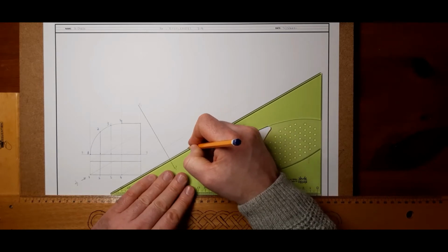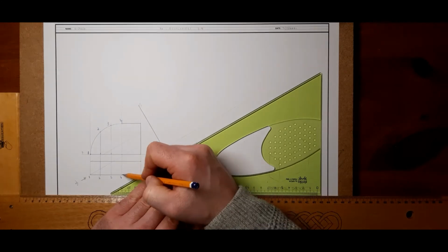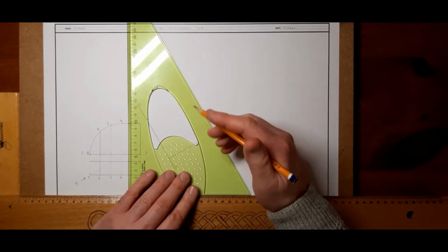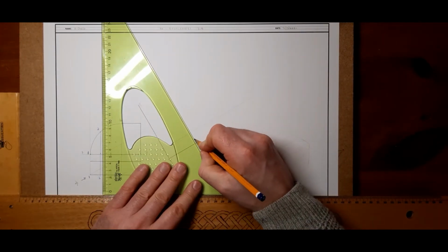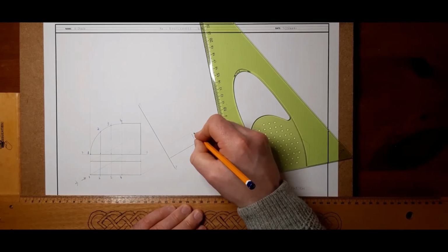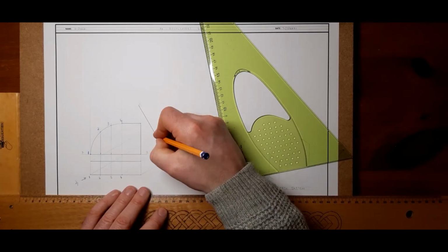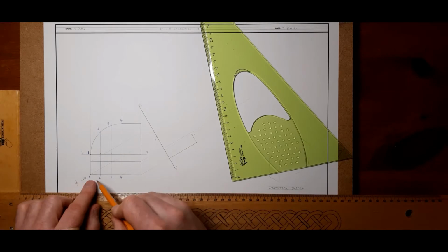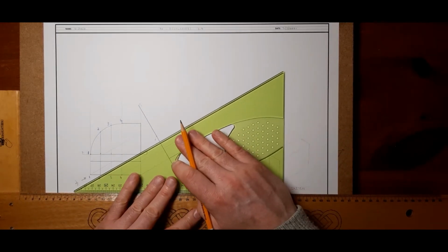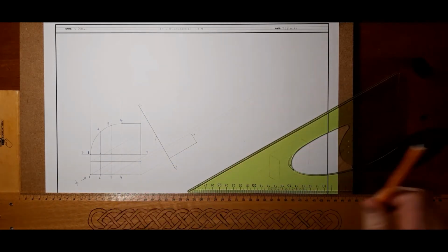So I can draw on that heavy. I know then there's a level flat piece coming over as far as there. That is in plan view. Okay, so if I bring over that line now, that's how far over it comes. Follow that guy up, and that's actually 4 there at the top now. We also have 1 down on the bottom here. This is on the near side to us, of course, now. And now we need to get points 2 and 3. So we go up 2, we go up 3, and they're somewhere along those lines.